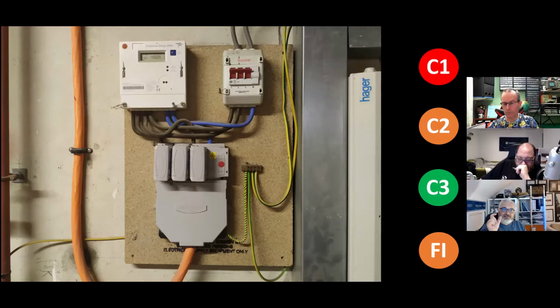And I have seen installations for years where there was a fault on the cable in the street. They've gone into the connected load building, swapped, say, the yellow phase onto the blue phase, doubled up them terminals, fixed the repair in the road, couldn't get back in and have left it. So it's another thing we need to consider when working on three-phase DNO heads. It's not just a simple issue anymore.